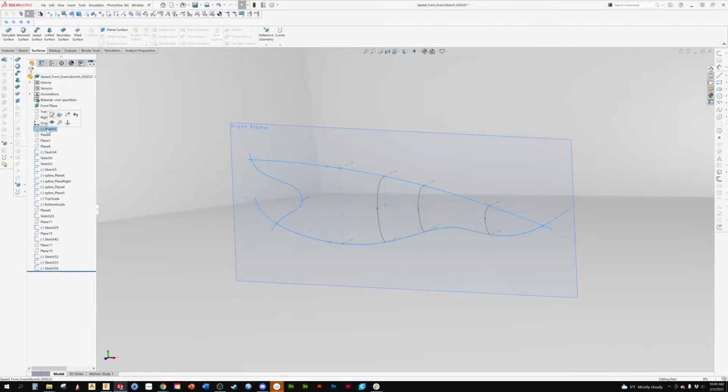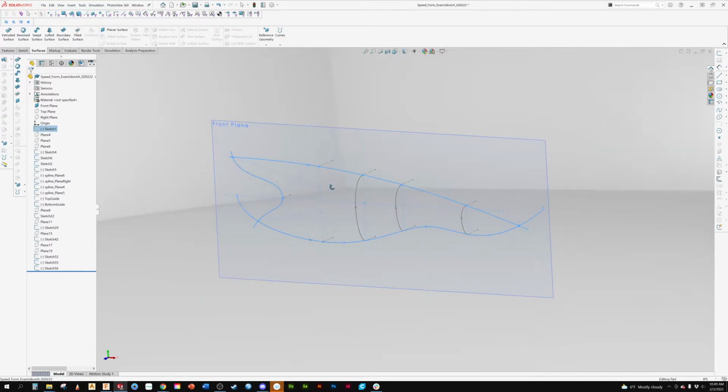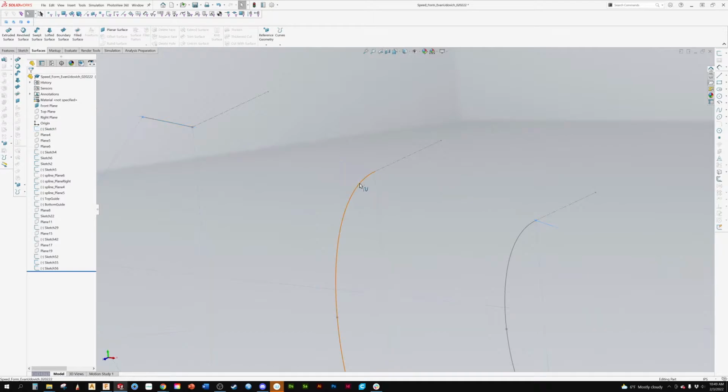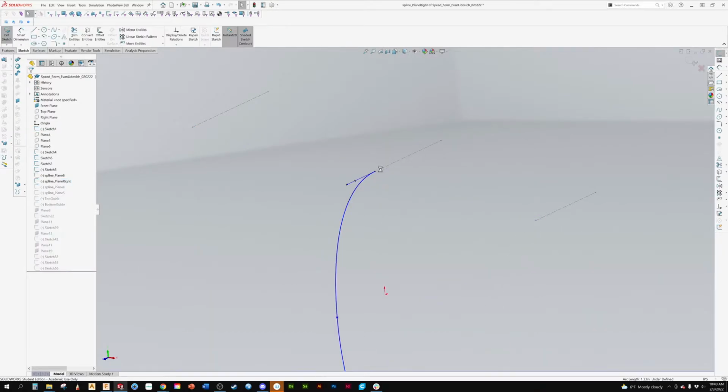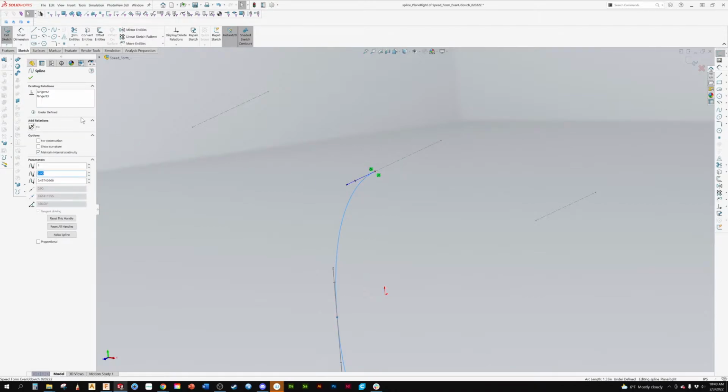If we look at this sketch, one of the things that I like to do, if I'm going to be mirroring this surface over the edge, is make sure, even though we can build curves, and as we look at these curves, we can say, hey, at this point we want it to be tangent, either by snapping to the guideline or making the tangency perfectly horizontal. And you can see what has been done here, which is a great start. If we zoom out here, same on the bottom.